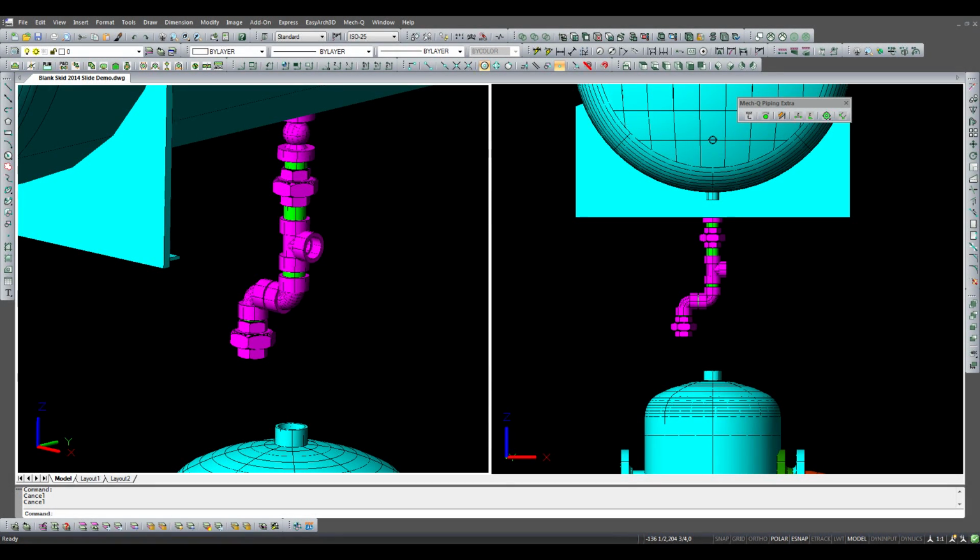What we want to do is slide the diffuser under the union above. Without the slide routine, we would have to either create temporary construction lines, then move the tank and erase the temporary construction lines, move the tank to the face of the elbow, then change the elevation of the tank so it sits on the skid's floor, or use the move command with point filters.